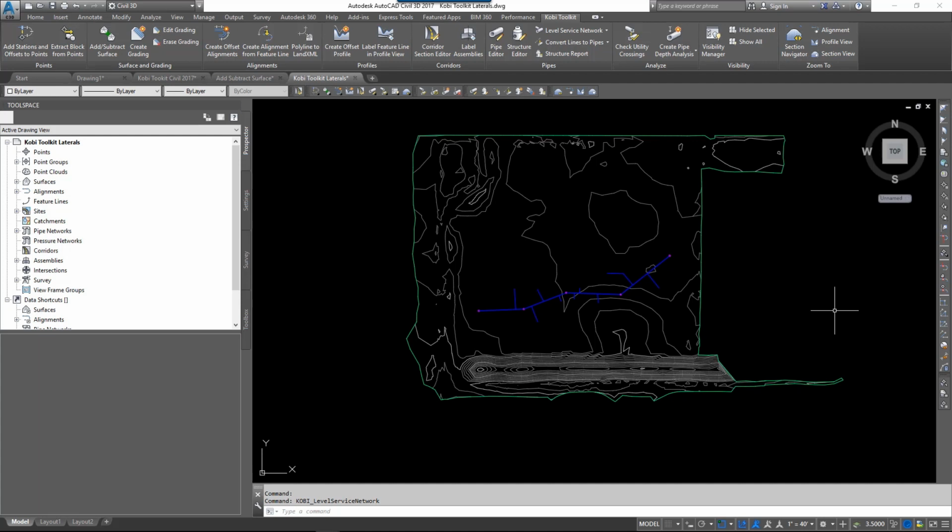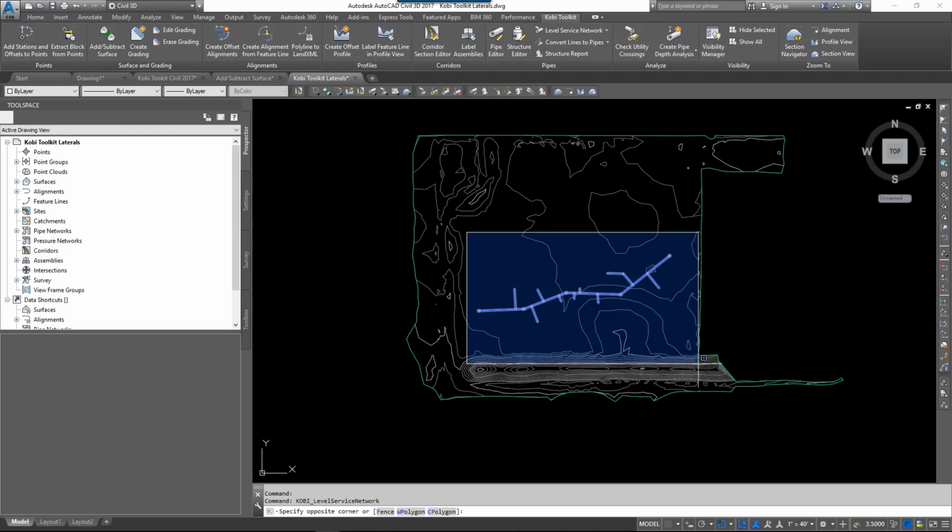Welcome to this short video on Level Service Network. The Level Service Network command allows you to set elevations and grades for all your service lines going into your main. Before I demonstrate this command, I want to show you what this looks like at the moment.